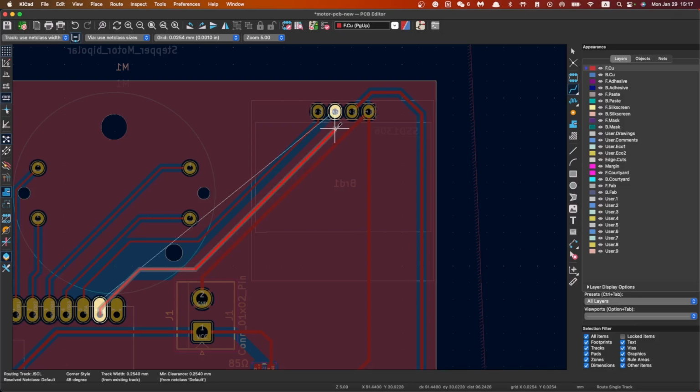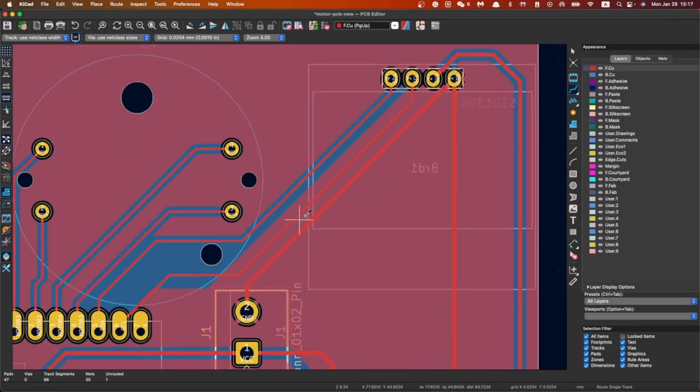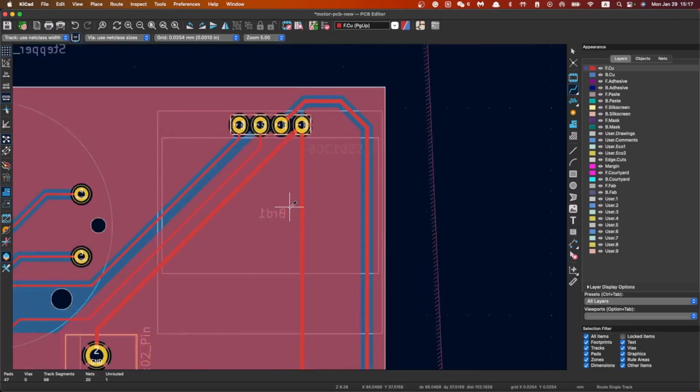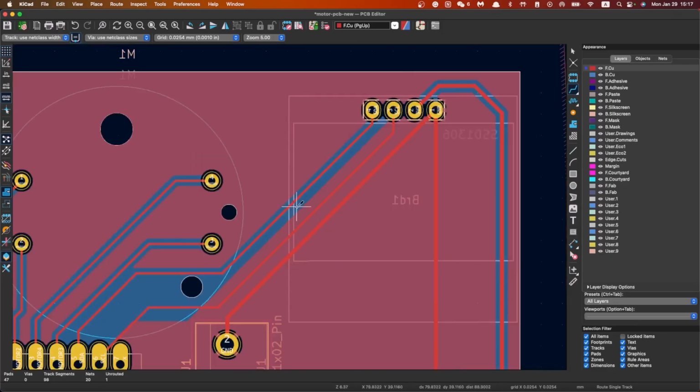It's okay that these tracks are a little bit close because you can control it. You can just use a tweezer or any other tools to clean those gaps between the tracks. That would be easier. But if your track is being drilled and cut off, you cannot save it at all.